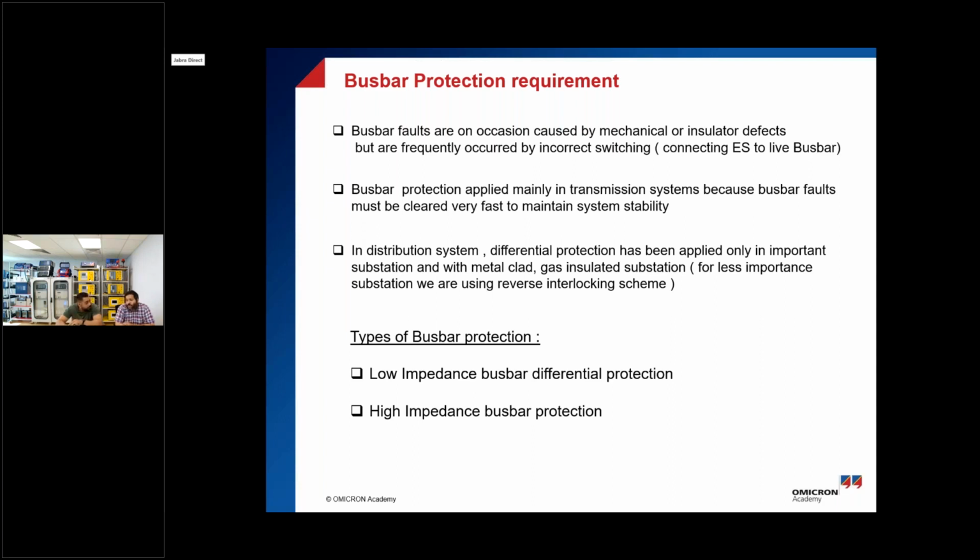It causes huge damage because it's very close to the main busbar. Yes. And this will be a big failure and loss of energy. And exactly, there will be no fault resistance, or there is no impedance to limit the current. The short circuit level would be very high.